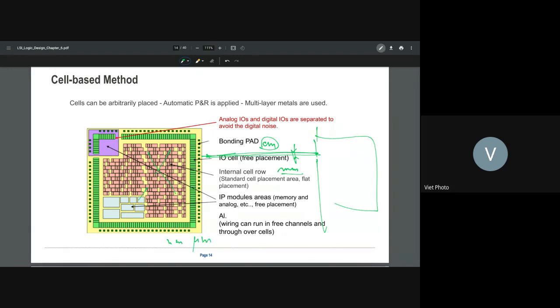You see that? Whatever cells inside are driving, if they have to drive outside here, they will be dead because the load is too much. The load inside here will be in femtofarads, but when you go out here, the load will be picofarads. So you need a bigger guy in the middle as a buffer to be able to drive the outside world.